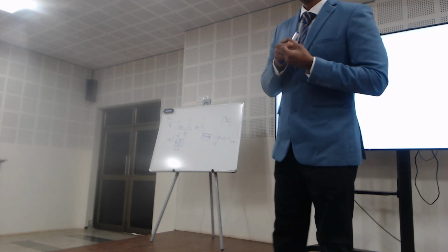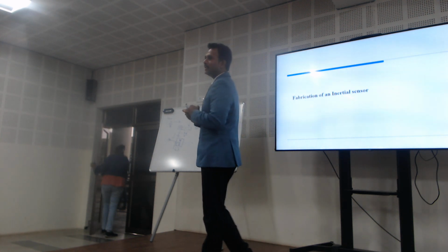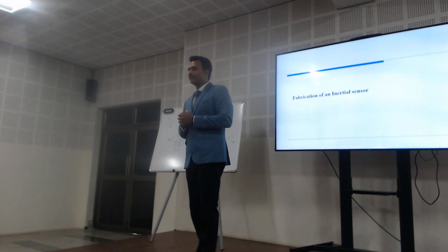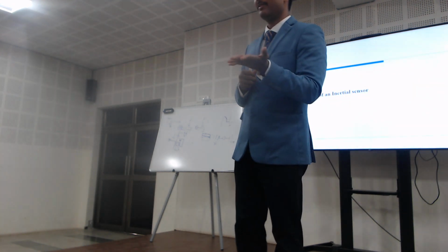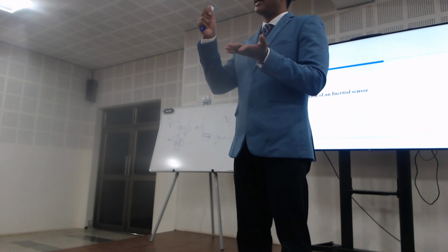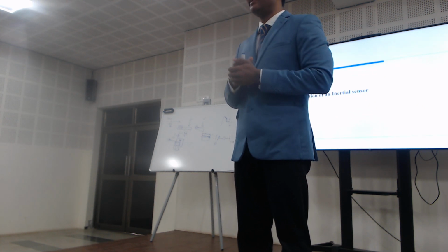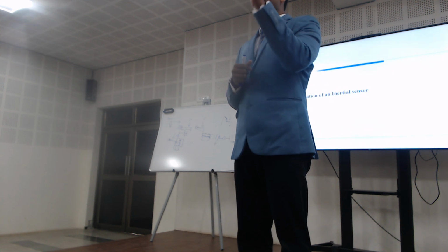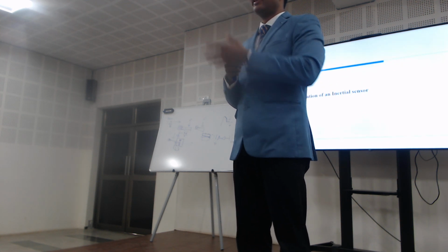Okay. Then what is the difference between normal fabrication and this separate fabrication? In normal fabrication, we start from a wafer. On that we deposit layer by layer, we etch, again we deposit, again we etch. Like that we get the final design. But in SOI MEMS, a predefined three-layered wafer is already available.